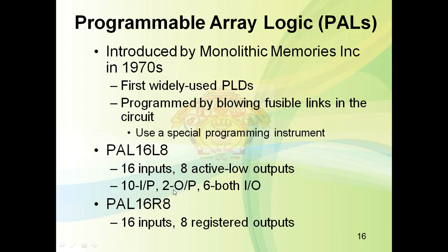Out of that 16 input pins, only 10 are input pins, 2 are only output pins, and the remaining 6 serve as both input and output pins. So 10 plus 6 gives the 16 input pins, and 2 plus 6 gives the 8 output pins.